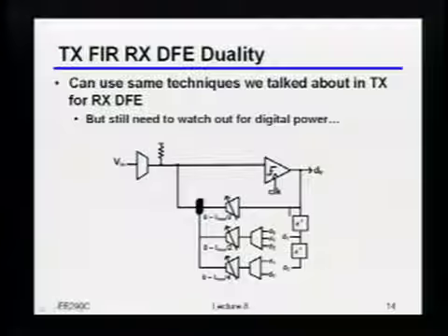Anything you do will also have implications on what the digital feedback delay may end up being, which is absolutely true. So, by the way, for most of the technologies I've seen, it turns out that you can actually do some pretty complicated DFEs, so that most of the time actually doing this stuff in the digital domain probably isn't worthwhile. But if you push on the speed enough, so that it's just not feasible to build this thing anymore, those types of techniques may become just a necessity just to make it even possible for you to actually get the DFE to work at this speed.